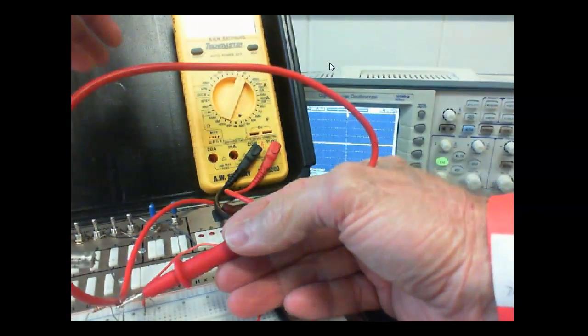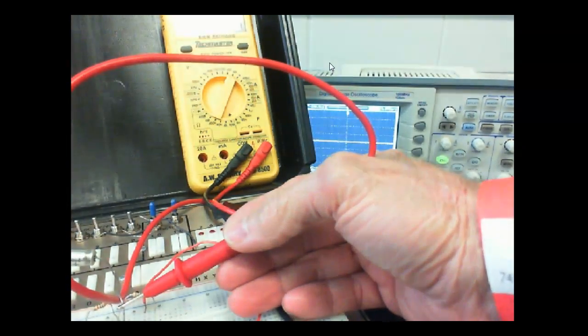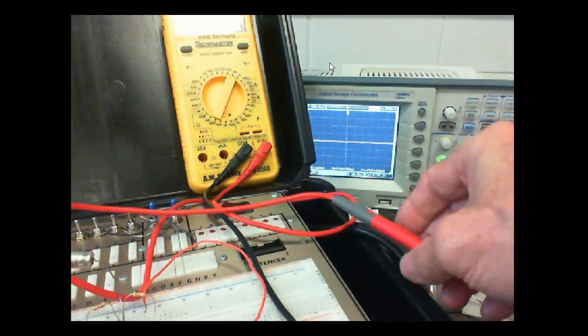Okay, so here's my capacitor. I'm going to put the negative side of the capacitor between the two resistors, and I'm going to bring my AC signal in here. Then I'm going to measure the bias. So even though I'm bringing that AC signal in, my voltage is still set to what? 2.5 volts. So now it's not seeing it as a source.